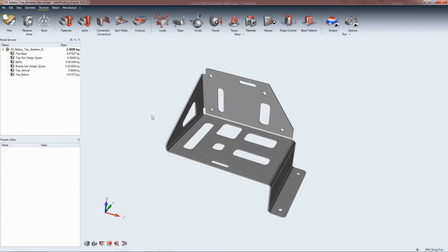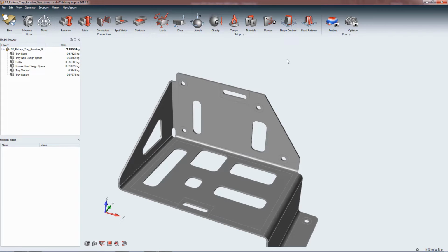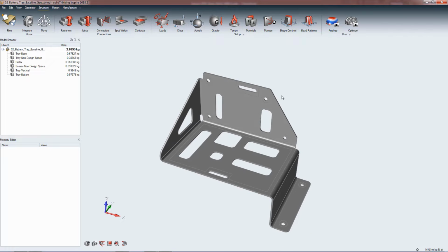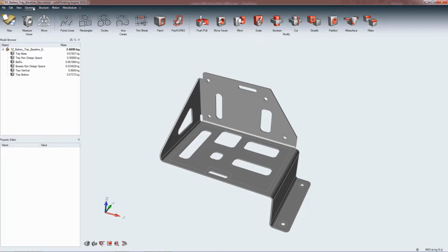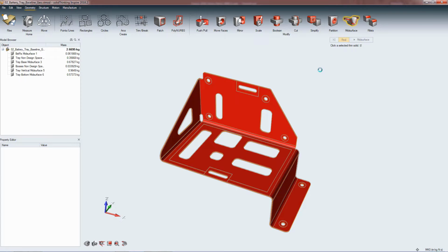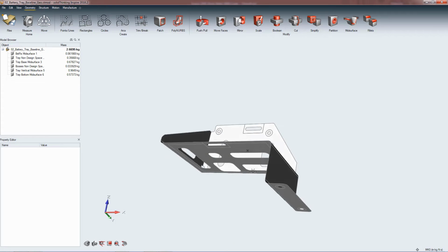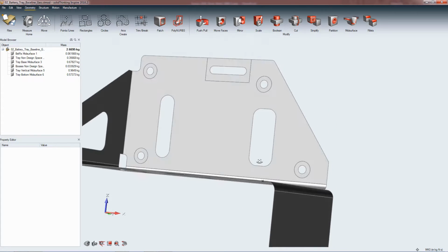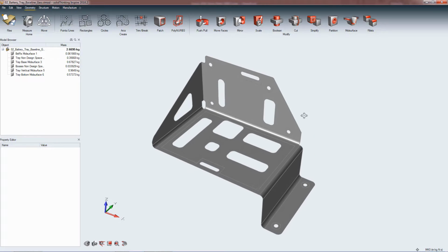The first step we are going to do is to check the performance of this baseline design, so we can check if there is room for optimization. First, I'm going to extract a mid surface to represent this geometry. It's in this geometry panel. With a few button clicks, I can get the mid surface very easily. Here you can see it's now all surfaces.